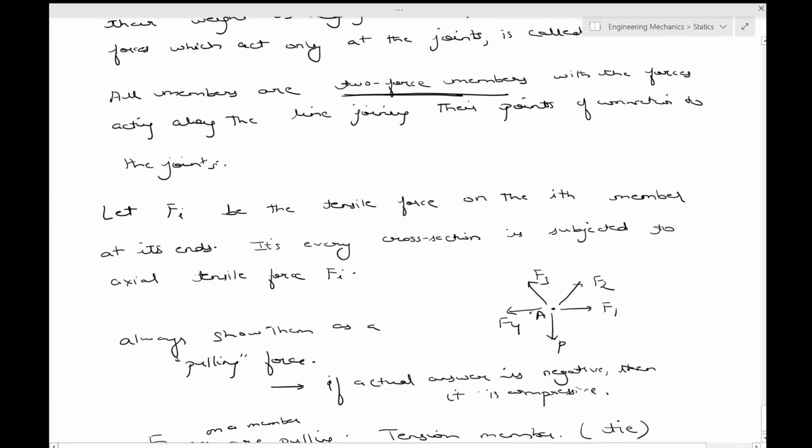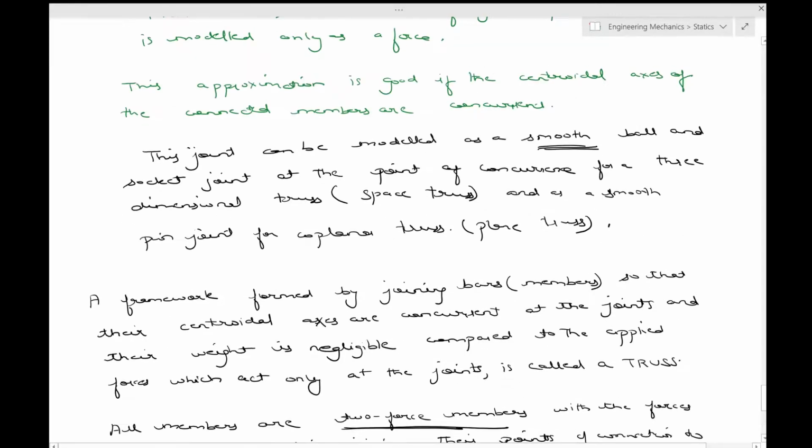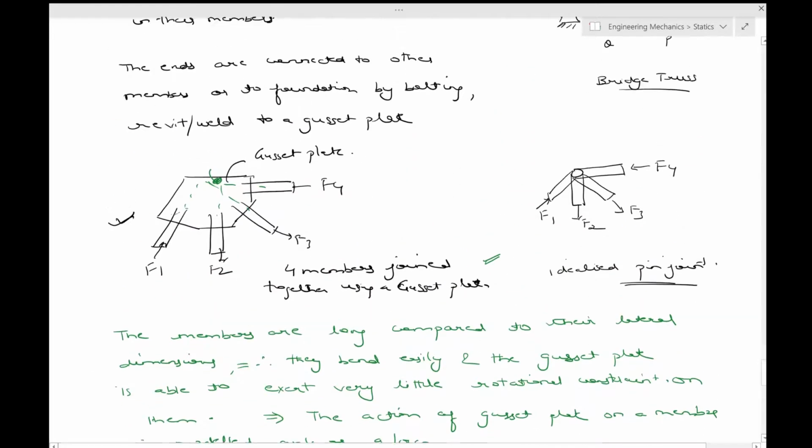One of the things I sort of forgot, I just told you about the idealized joint, but you can also have an idealized support. Say a roller like this. This means that this particular support is only allowed to move in the horizontal direction.